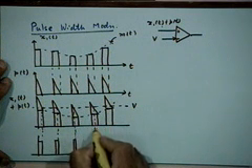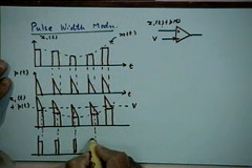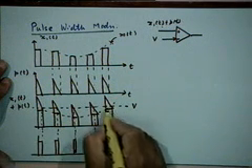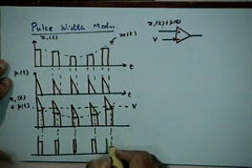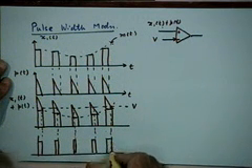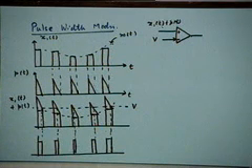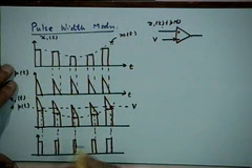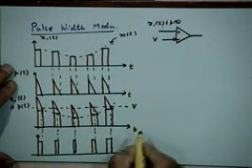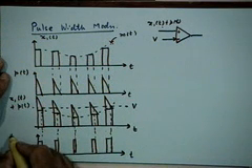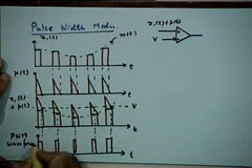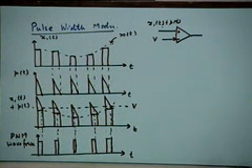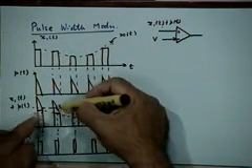As you can see, the width of the pulse that you will generate will be proportional to the amplitude of the pulse on which the triangular pulse is riding, and that is precisely what you want. So, this becomes your PWM waveform. Are you with me? In fact, it is obvious because of the fact that this is a triangular pulse.